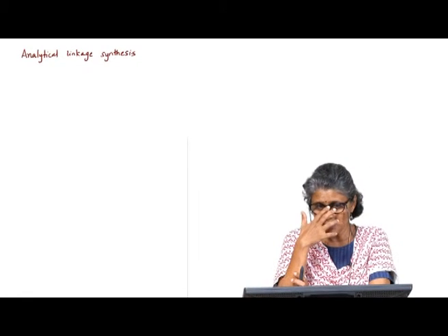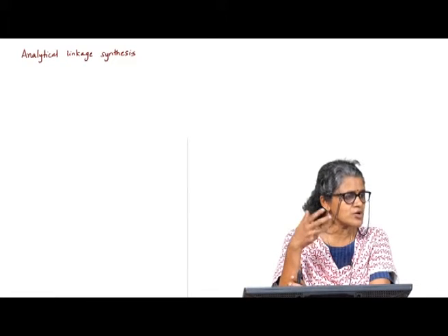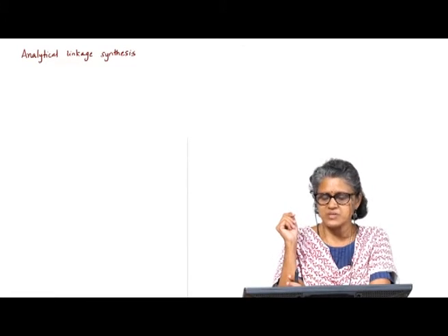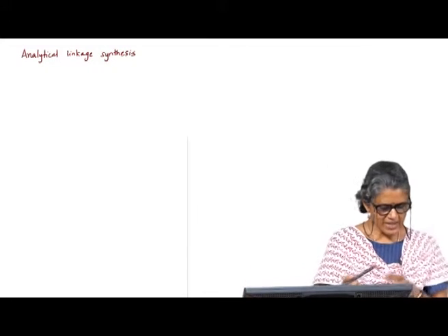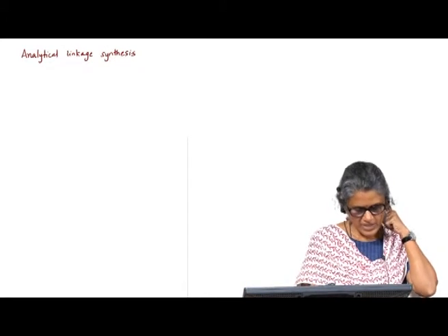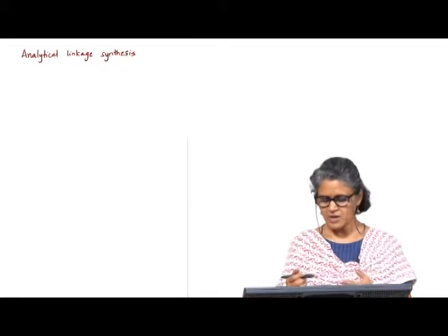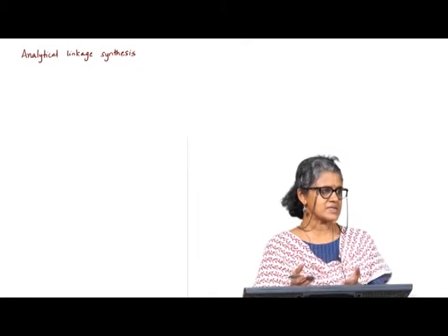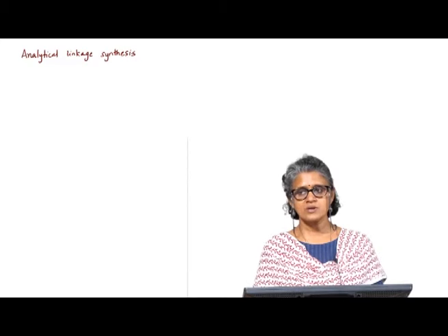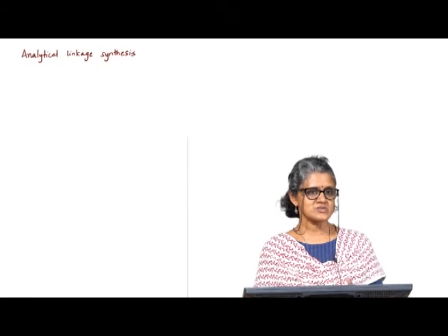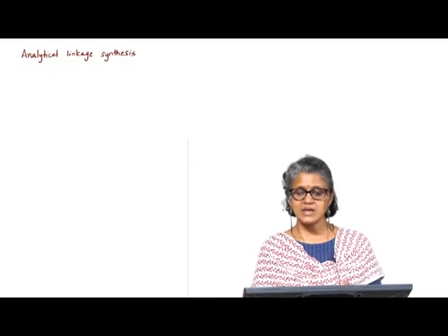Analytical methods are more difficult to set up, but they give you more power, more control over the design variables. So that is what we will be looking at. When you want an optimal four bar for a particular application, based on specifying the link length ratios or the transmission angle as I mentioned, then you want to explore analytical methods for synthesis, because they can help you put constraints on some of the design variables more easily.